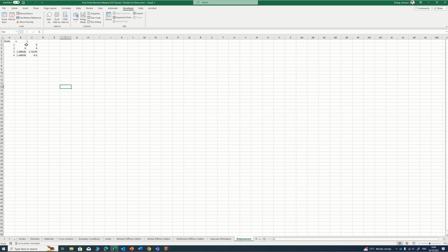So the displacement now is showing in there, for x direction, y direction, and then that's for node 1, node 2, node 3, node 4. Okay, so this is the information we're going to maybe come back to after we use the Autodesk Robot to check all the detail. They should be very, very close, maybe just a rounding error difference between them.